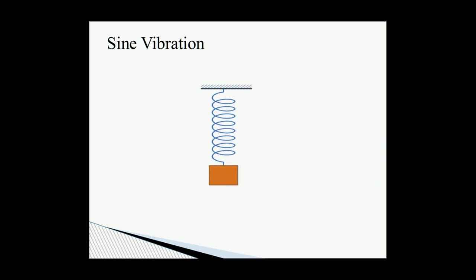Stop. Now, if you counted correctly, you should have 10 cycles. Is that correct? Okay, well, you have 10 cycles. I have 10 seconds. Let's go ahead and divide 10 cycles by 10 seconds, which gives you a resonant or natural frequency of 1 hertz. So therefore, this spring mass system is moving at its natural frequency of 1 hertz, which also explains why there's so much displacement, because at lower frequencies you have higher displacement. Okay, let's go ahead and move on.